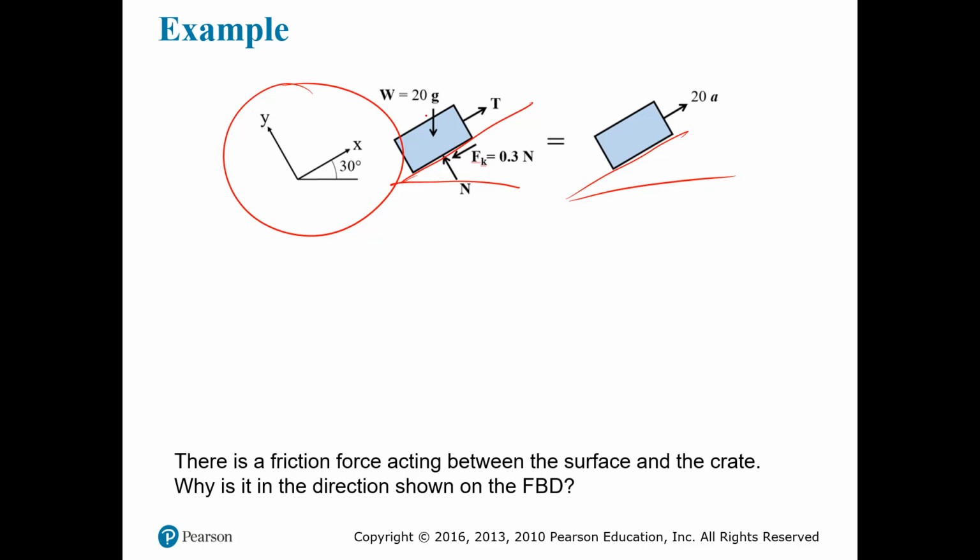And again, this is the free body diagram, and this is the kinetic diagram. It's very important that you place them both so you can understand exactly what needs to be done in order to solve this exercise. So just by looking at it, I know that I will have to do a sum of forces in the y direction, and it's positive for me going that way.